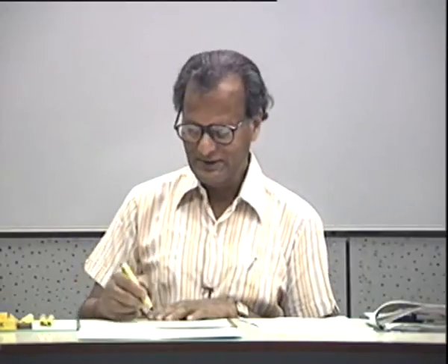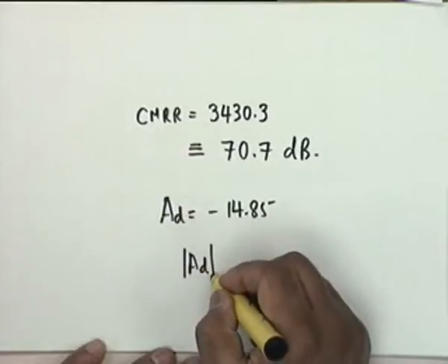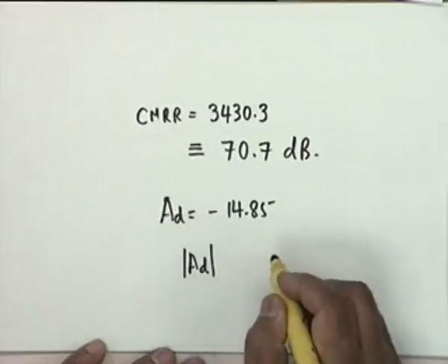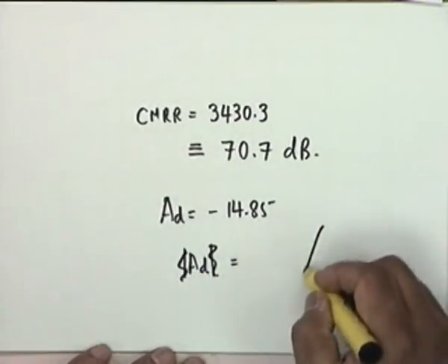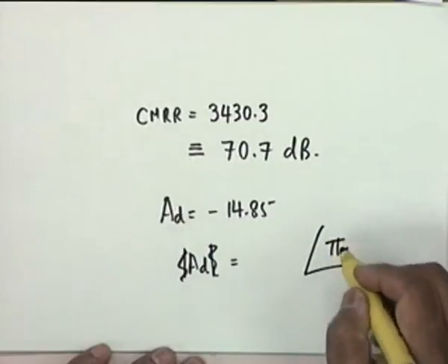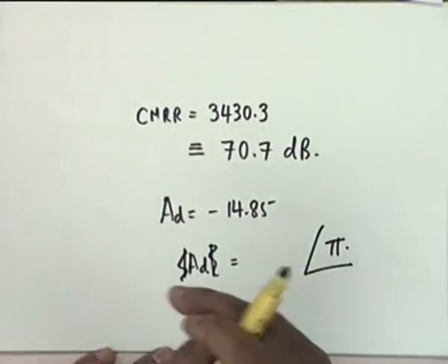You take the mod, you either express AD as mod, so many dBs, or you say AD equal to so many dB, then angle pi. Okay? Don't say minus so many dBs. No, that doesn't make sense. Minus so many dBs means what? That means attenuation. We always say minus 3 dB frequency. Alright? The attenuation is 3 dB. Okay. These are things that an engineer should remember.